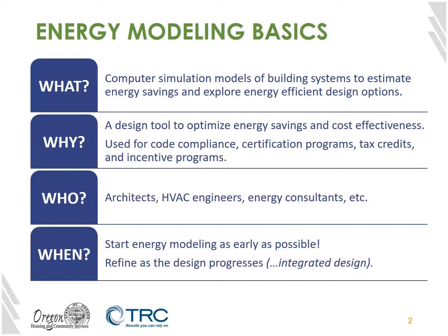Why do energy modeling? Energy modeling is a great design tool to help your project team optimize energy savings and cost-effective measures in your project. It's a great way to explore different design options and help to estimate projected energy usage of your buildings. This is especially useful for affordable multifamily projects to determine energy costs for both the owner and residents. Energy modeling is used for code compliance, certification programs like LEED, tax credits, and incentive programs like the Multifamily Energy Program.